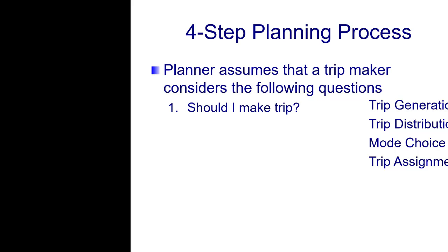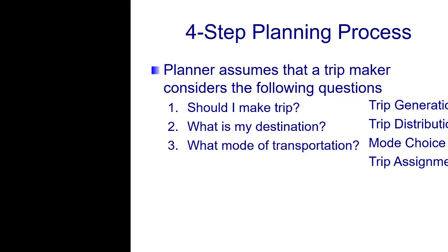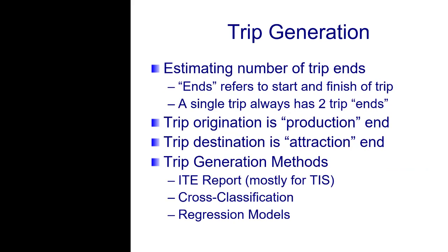1, should I make the trip? That's trip generation. 2, what is my destination? Trip distribution. 3, what mode of transportation? Mode choice. 4, what route do I take? That's your trip assignment.